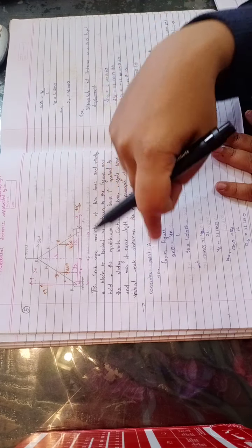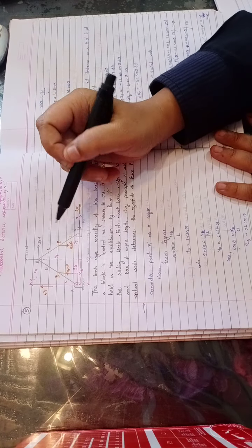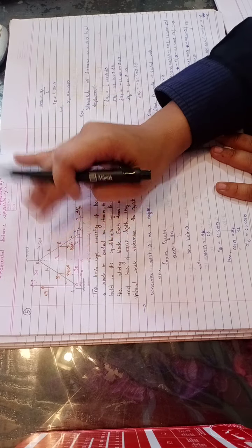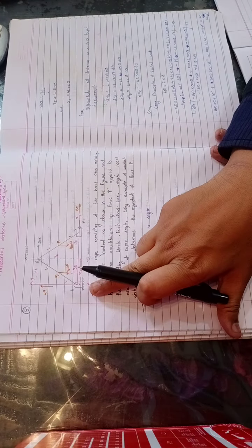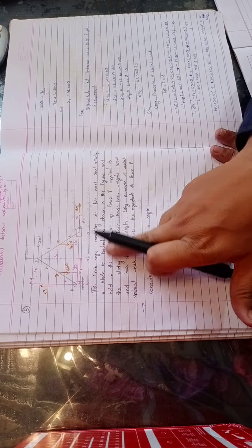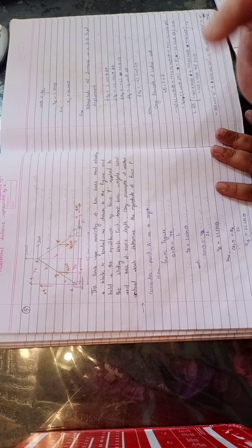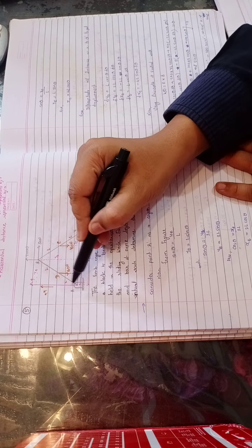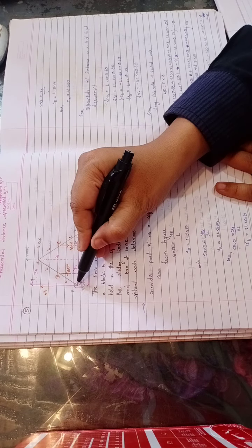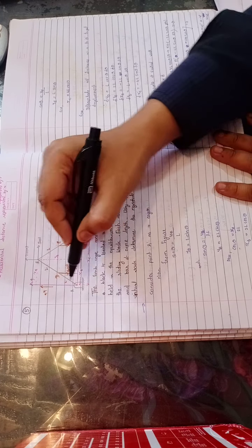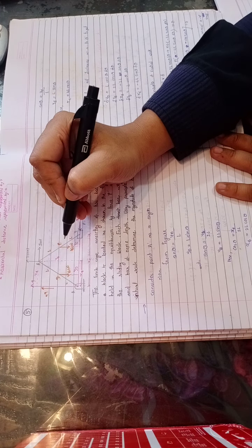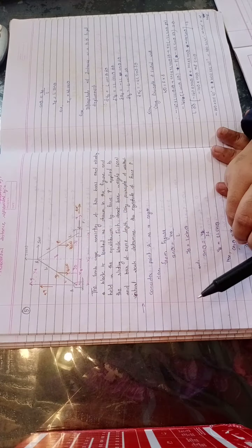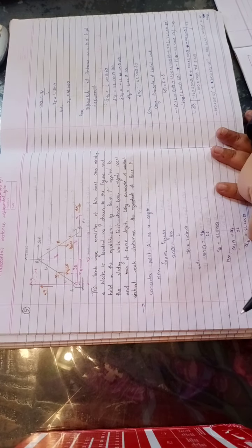So in this kind of problem we have to decide the origin of the figure. We may decide A, B, C, D or E, but if we decide either A or C, it will be very easy to solve the problem. So the best way is that we decide A as the origin of this figure. Once we decide A as the origin, we will draw one vertical line that is represented as the y-axis and another horizontal line that is represented as the x-axis from the origin.